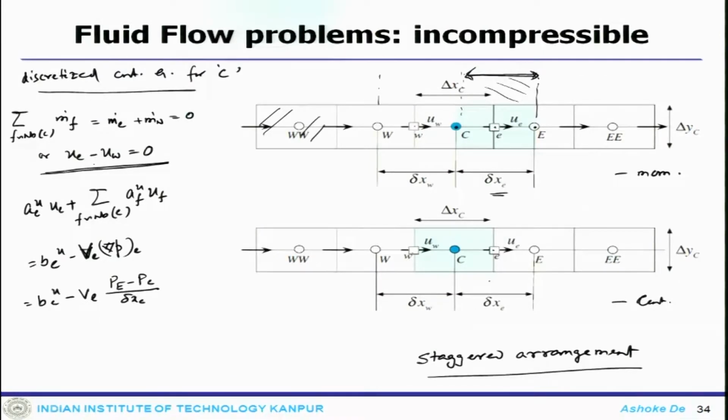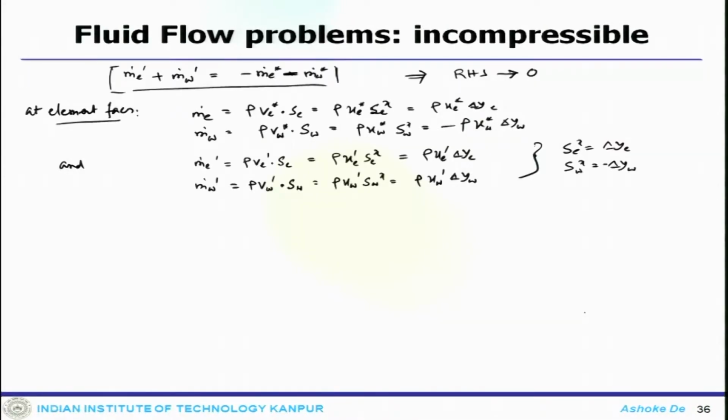As long as you are in this kind of one dimensional stencil, this is what you can use. Now, the pressure field does not appear in this equation nor the equation written here, so we have to bring the pressure field into the system.